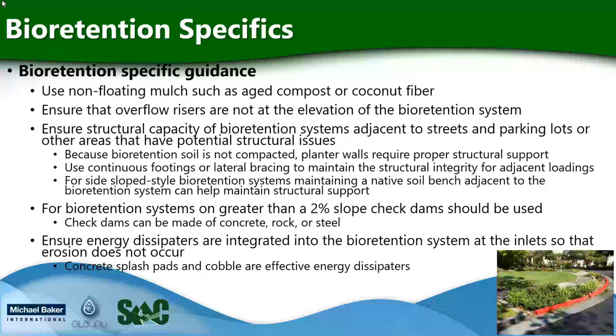We also want to ensure that the structural capacity of bioretention systems acknowledges the adjacent land uses, whether they be streets or parking lots or other areas that have potential structural issues. Because bioretention soil is not compacted, the planter walls will require proper structural supports. So use continual footings or lateral bracing to maintain structural integrity.